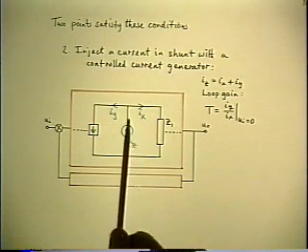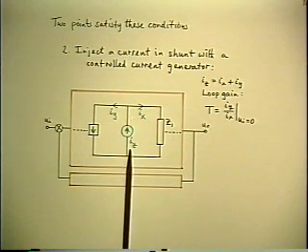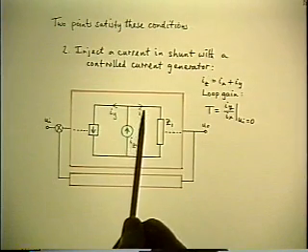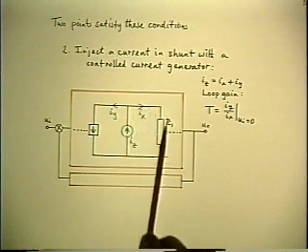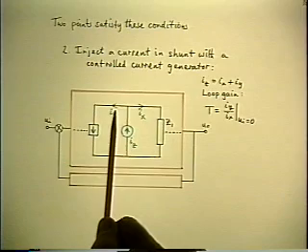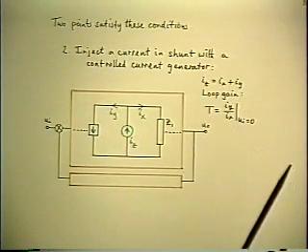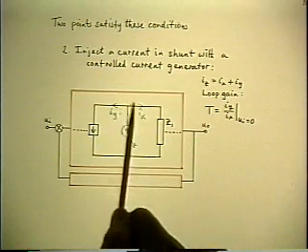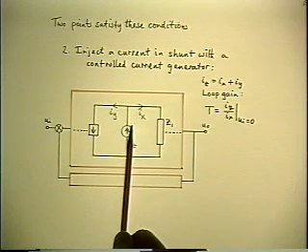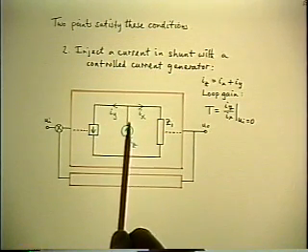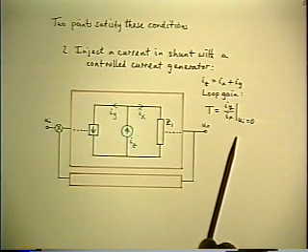You can inject a shunt current, IZ, and it splits into two currents, IX that goes forward, and comes back up again as IY, and the loop gain is IY over IX. And there is a phasor triangle of currents, just the same as there is for voltages, and the loop gain is the ratio of two currents.